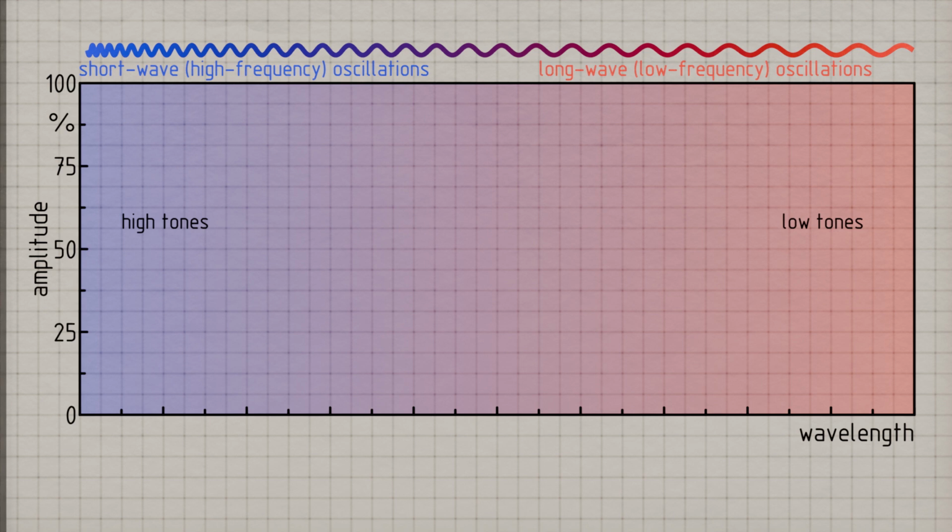Filtering a probe signal works basically like filtering a sound signal. Similar to an equalizer, which dampens certain frequencies or wavelength components in a recorded music to create a specific sound, unwanted wavelength components in the recorded surface probe signal can also be dampened using special profile filters. Noise influences in the scanned surface signal basically correspond to high tones, while form deviations correspond to low tones. In between lies the transition from roughness to waviness.